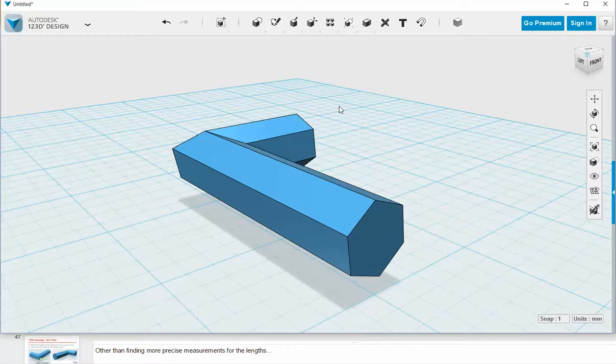It said invalid operation for profile being hex. Make sure that you selected your hexagon correctly. If you don't have it selected correctly, it might just be thinking you want to select an edge of it. Also make sure that you're drawing on the correct planes. Make sure that your polyline's on the workspace and your face is coming out of the workspace essentially. Alright, good point. When defining the profile, you can click on the white dot in the center of the polygon, which I've erased the sketch of, but that'll definitely work.